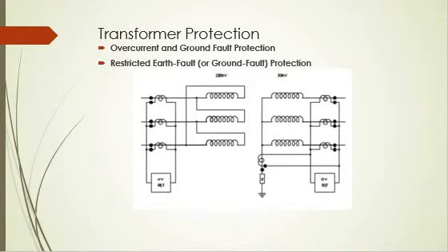The ground fault relays must be set above the maximum zero sequence unbalance that can exist due to single phase loading. Overcurrent relays or fuses must protect the transformer against damage from through faults. The setting should be coordinated with the transformer damage curve and with the relay settings on the adjacent element.